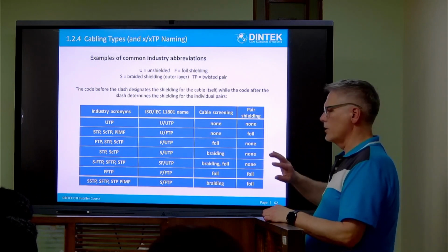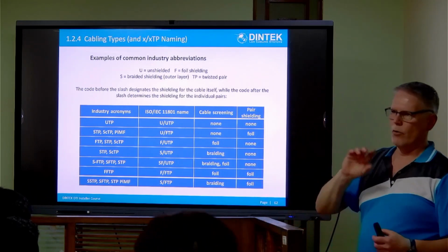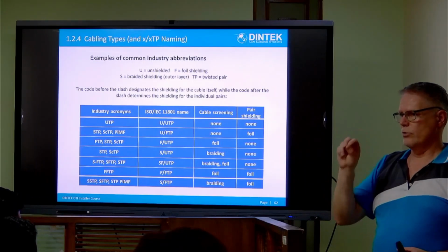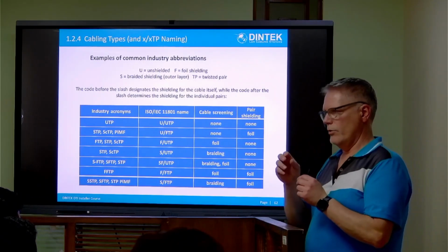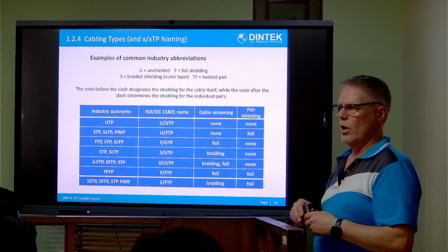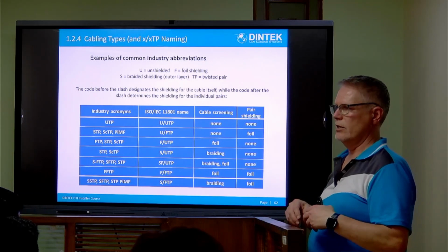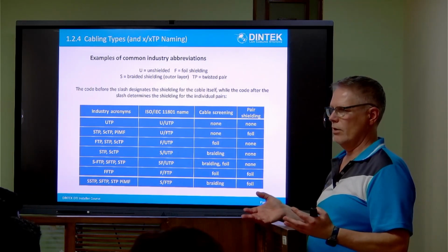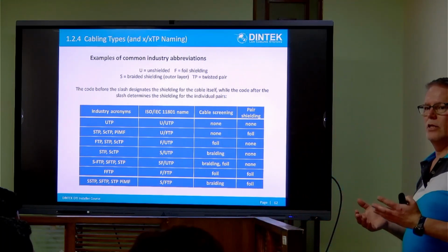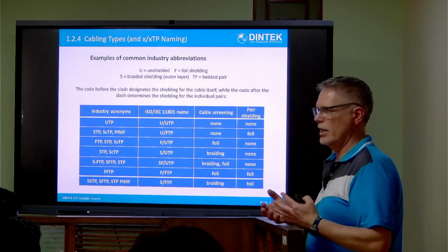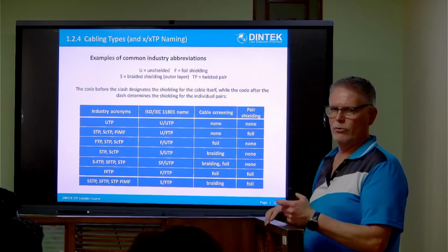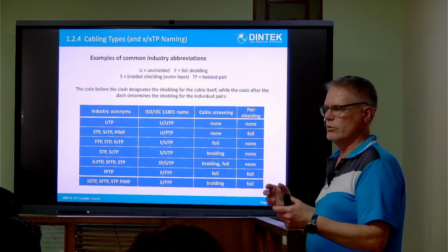Although there are two other types you can use, which is foil-wrapped, unshielded four-pair, so foil around each pair. That's dealing with high amounts of interference between pairs in the cable. Or if you were dealing with interference from outside, say an environment with a lot of electrical motors or machines and a lot of electrical noise, you just want to shield the cable itself, so maybe you go for a foil-wrapped unshielded cable.